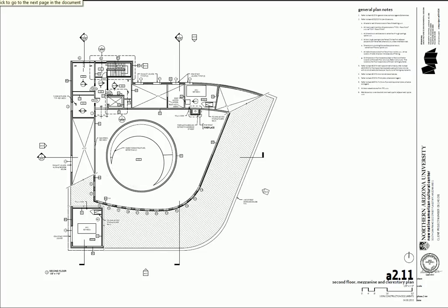We go up to the mezzanine, and what I'm seeing in this X here shows an opening. This looks like line of roof, so there's a cutting through a roof here. These cut lines here indicate that we're slicing through it. That's probably the slope of our roof. And then over here it looks like we've got a stair going up, a little elevator shaft, and then these are the details I was talking about.